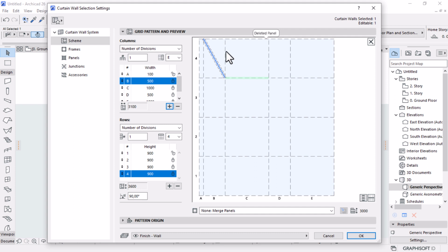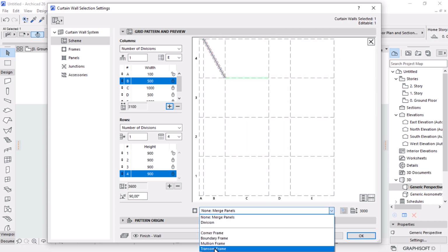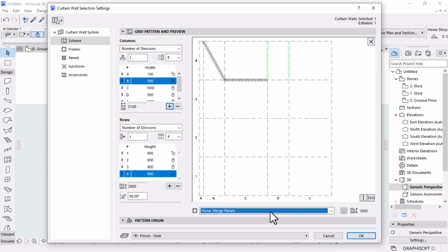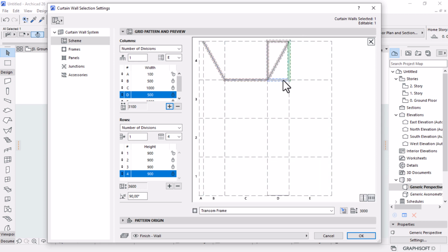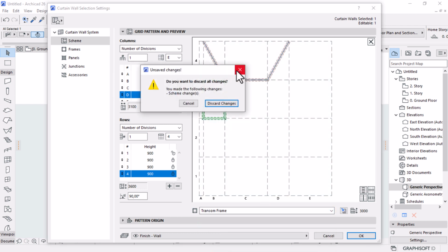Okay, and then for this, I'll have a straight transom, and then this side I'll have a transom, and also for this I'll have a transom. If I can manage to select this panel, I'll add another transom at the top so that this panel can be independent. So I can now add another cross opposite like that. So I can now go back and select all these unnecessary frames, delete them, because they're just meant for creating this. I could achieve this as a mirror downside. Okay, so let's select that, this, and that, add this as a transom, and then sorry about that.